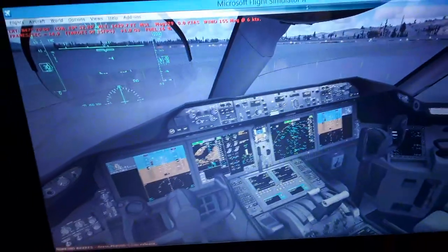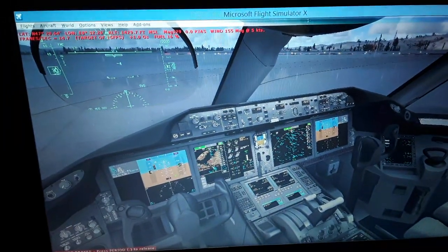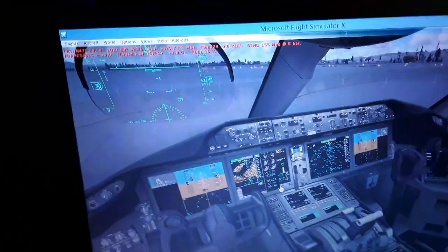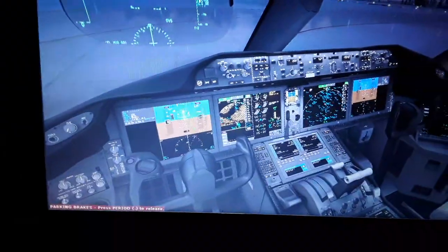We can align using the inertial reference system and the flight management computer to make an inertial alignment. We have also the magnetic north pole and the geographic north pole, and magnetic variation depending on where we are in the world. We have the display of the horizontal and the vertical profile of the aircraft as it flies. Also we can see in the navigation display, when we're going to create the flight plan, you will see it displayed with a purple line, and one waypoint by another is going to be connected as the legs of the flight plan. So we have also in the navigation display the display of other aircraft that